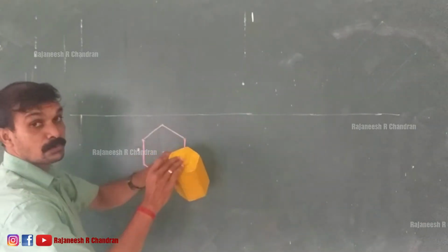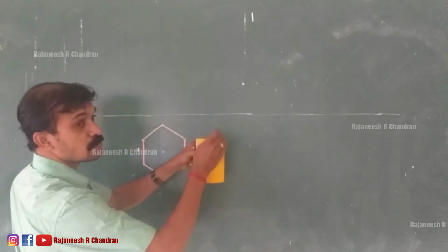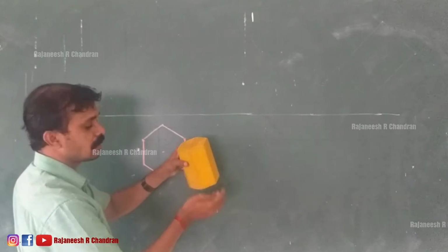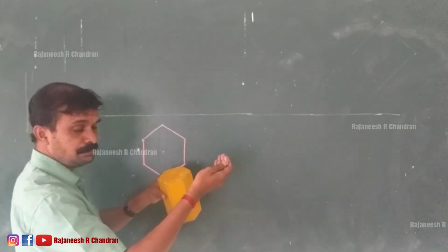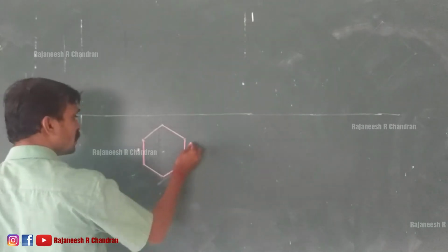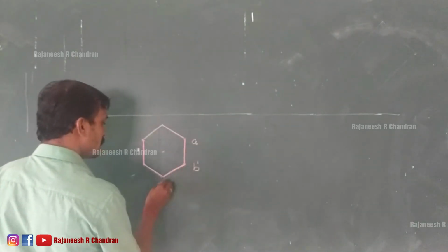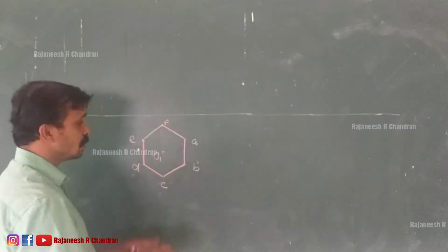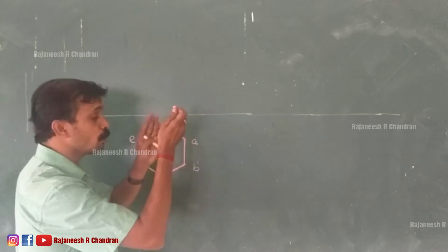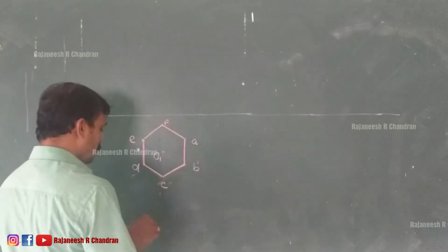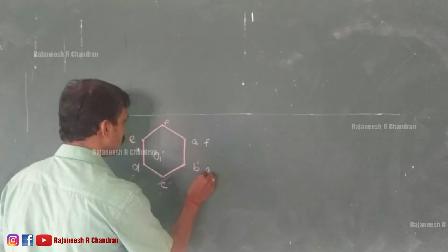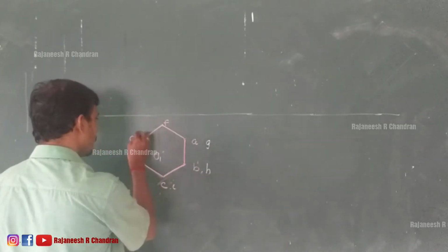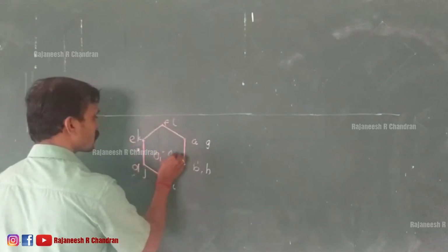for the hexagonal prism two faces are there, this one and this one. Actually we have drawn this face and that can be named as ABCDEF. The bottom can be named as GHIJKL. So here A, B, C, D, E, F, and the center is O1. So A, B, C, D, E, F belong to the top hexagon face, and G, H, I, J, K, and L, with the corresponding center O2.